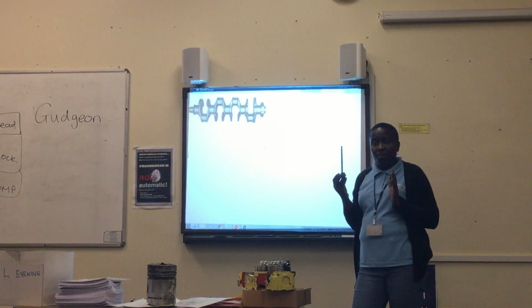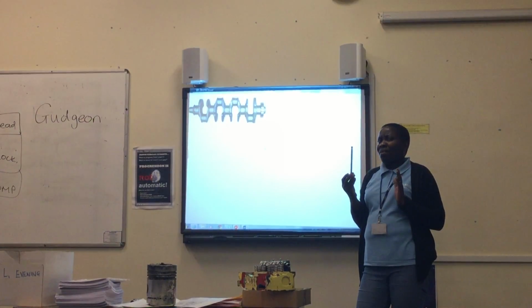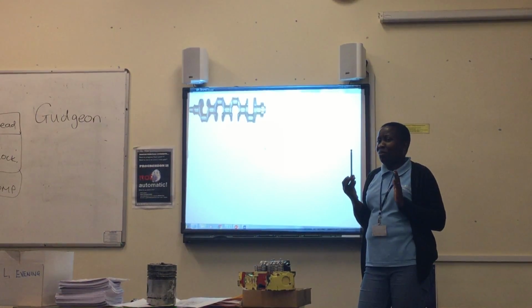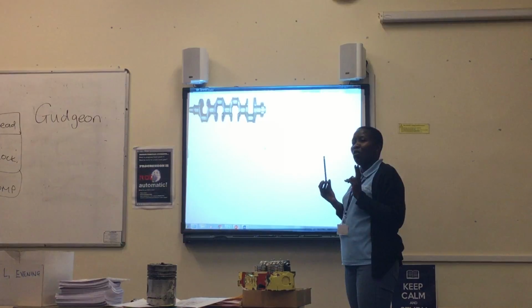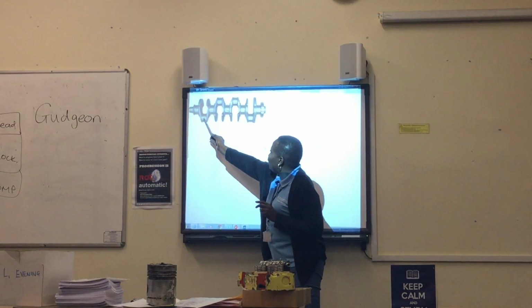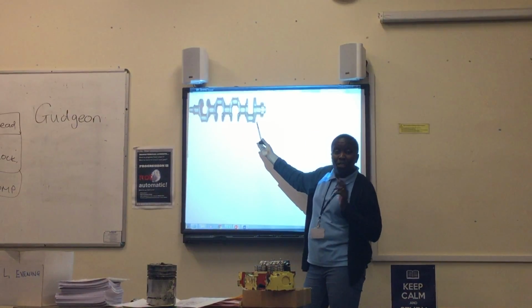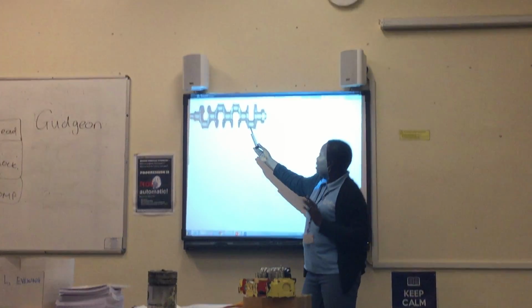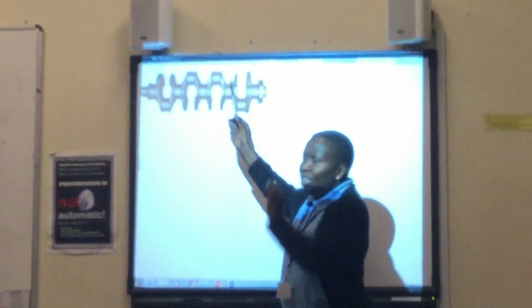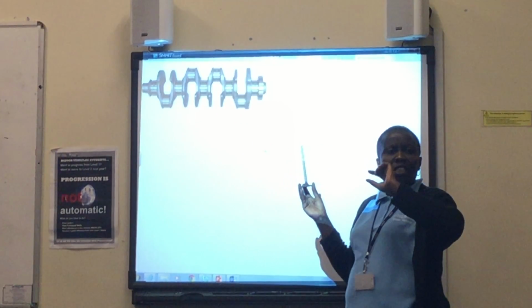Can you see the setup? 1, 4, 2, and 3. Remember what I said about 1 and 4 being married. Can you see that this journal is in line with this one? That is what makes 1 and 4 married. Then 2 and 3 are at the same position.